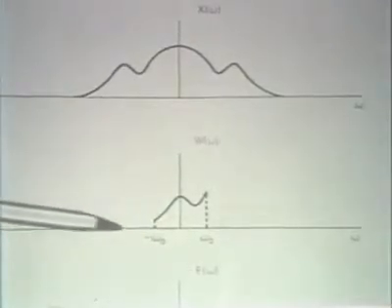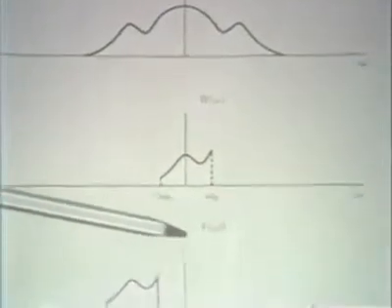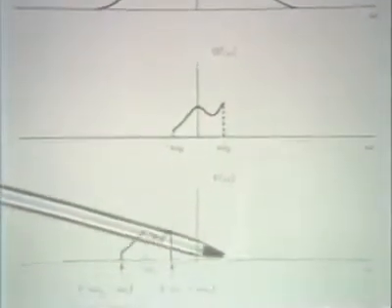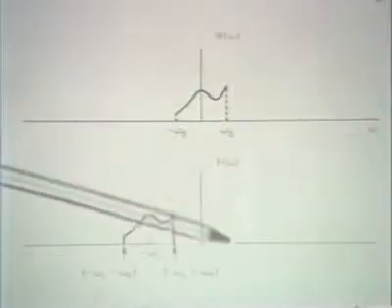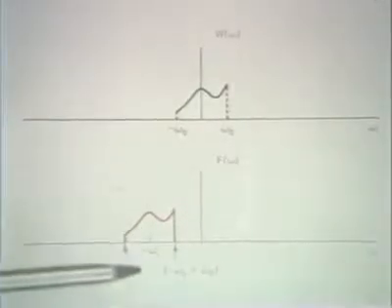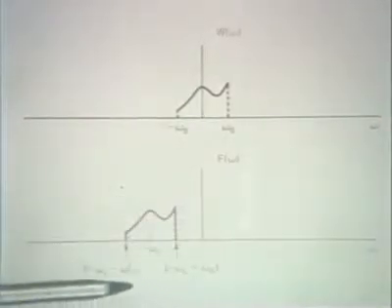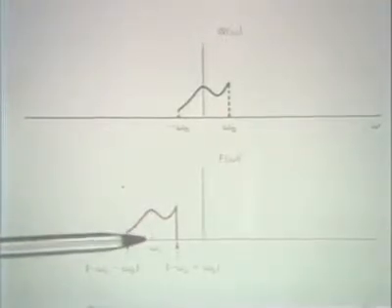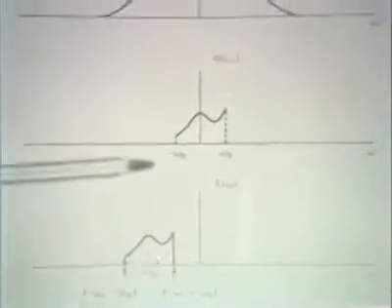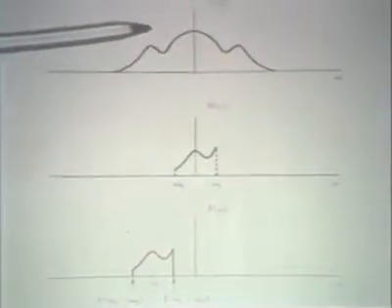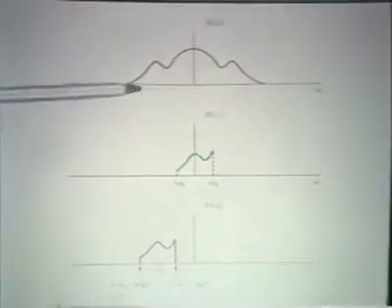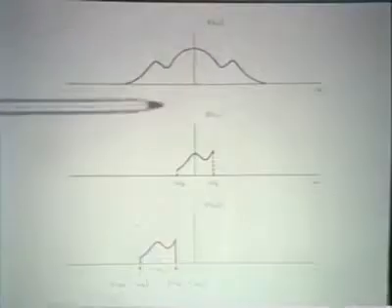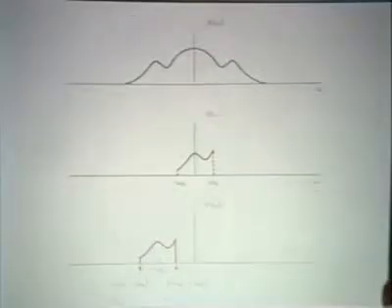And so that result will be what I show in the final result, which is here. And what we can see is that this, in fact, is equivalent, if we look back at the top spectrum, to having extracted with a bandpass filter a section out of this part of the spectrum.